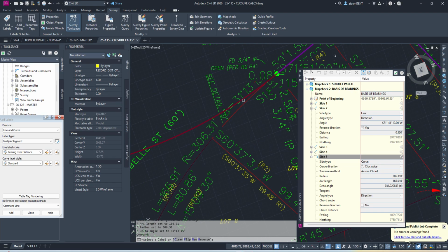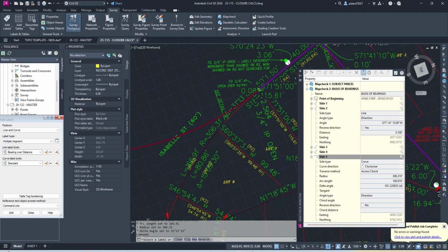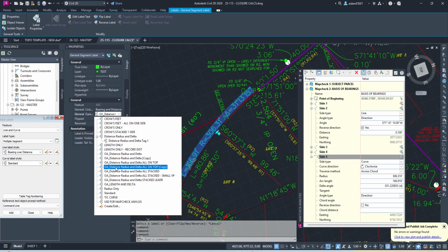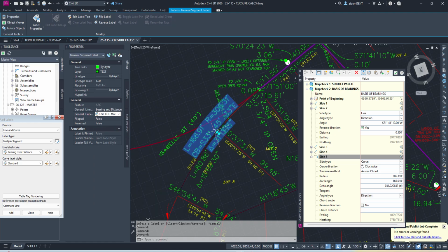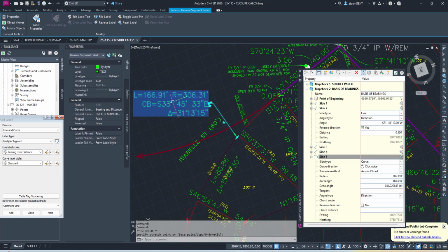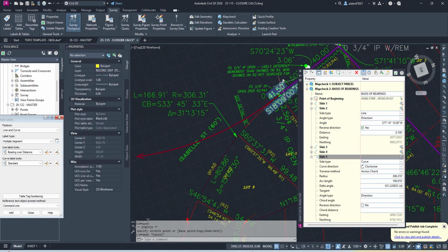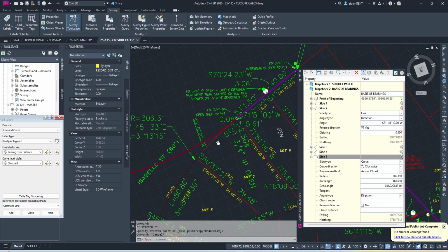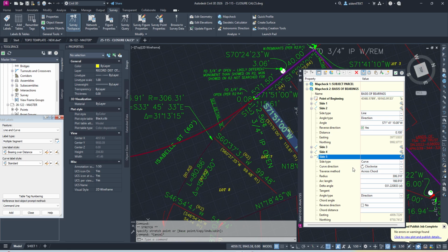You can hit this curve here. Curves is where you need to watch out. So if you don't have a curve on a tangent, you need to give it a chord bearing. And so we have one of these, I call it use for map check. This has a chord bearing here. See the CV is a chord bearing. That'll tell the software how to rotate that curve. But since this should be on a tangent, you don't need to do that.